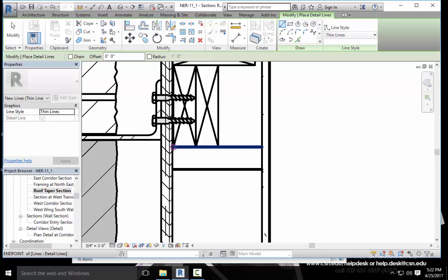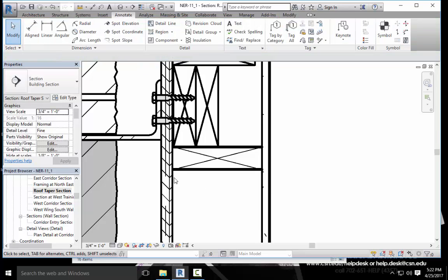And we're going to draw the X for this piece of blocking. Now you may say, hey, we just inserted this 2x6. Well, this dimension here is not a regular dimension. They would actually have to take the piece of lumber and cut it to the right width. So you're not going to find a detail component that just fits in here. You may have to draw it out. But you can simply do that with lines. So now your drawing should look something similar to figure 11.46.